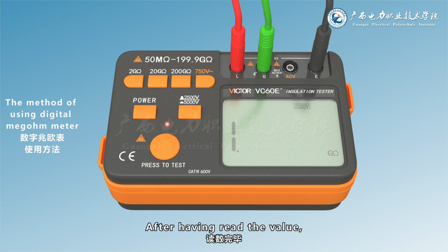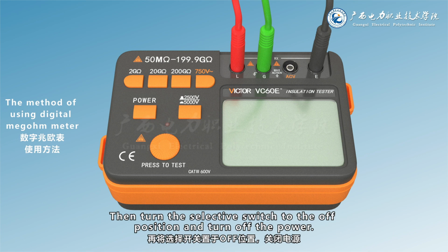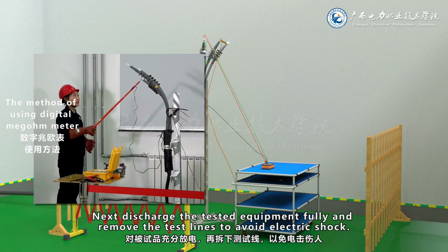After having read the value, you should press the test button first and then the power light of the Megger stops flashing. Then turn the selective switch to the off position and turn off the power. Next, discharge the tested equipment fully and remove the test lines to avoid electric shock.